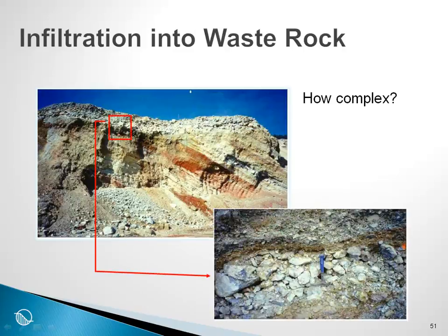And so if you look at it carefully on the stratification, it appeared that the coarse material was rather dry, but next to the coarse material in the fines, there was oxidation, and it would appear, looking at this cross-section of the waste rock pile, that the flow was taking place in the fine soils and not in the coarse soils.